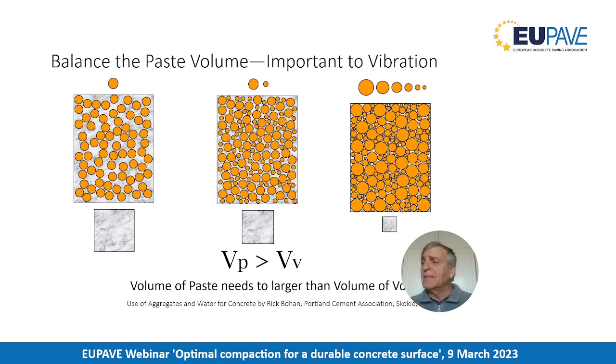I know that looking at optimization, these little windows right here become a little bit tighter, and if we get a little out of whack with how much volume we actually put in, we'll have issues that are really design issues in the workability system that are very difficult to overcome. A lot of the time it's just a matter of putting more vibration speed in to get more paste volume up to the surface, and it's a practice that has been recognized as needing to be limited.